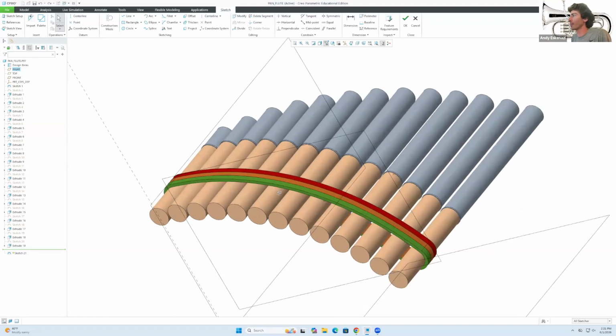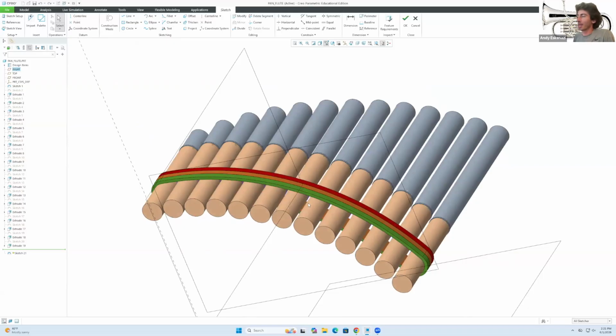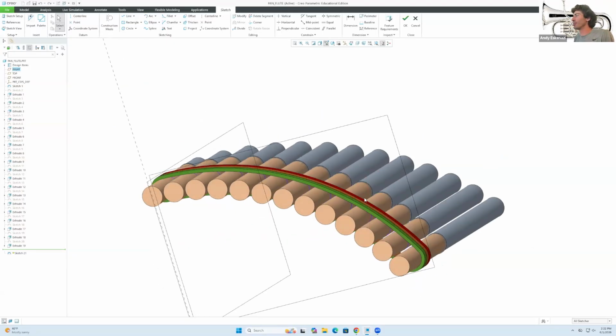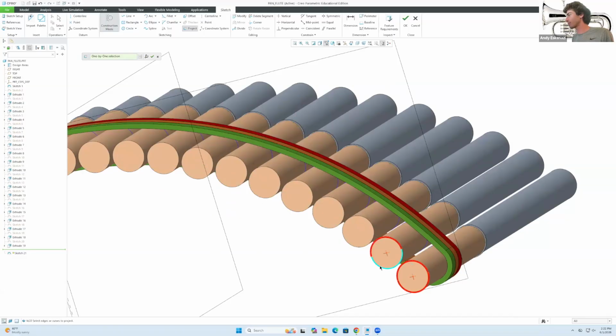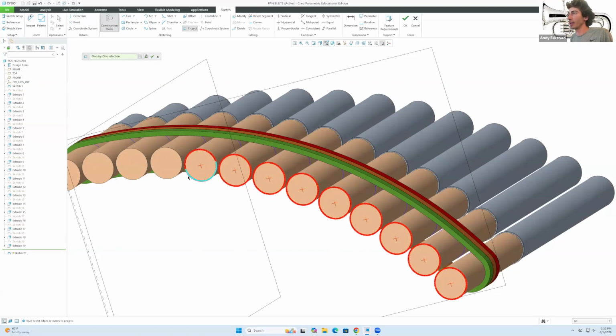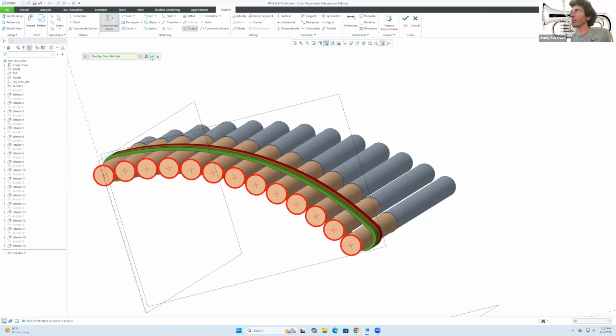And the way to do that, also one thing I will say is that I'm gonna assume that they're all gonna be stuck to this little band in there, but the way to make them all hollow is like this. So now again, we're gonna project all of these guys. So let me just actually do one by one. At least they're gonna be construction circles. And once I have them all laid out like that, what I can do is identify their origins, which is now being displayed, and draw another set of concentric circles that are going to be slightly smaller.